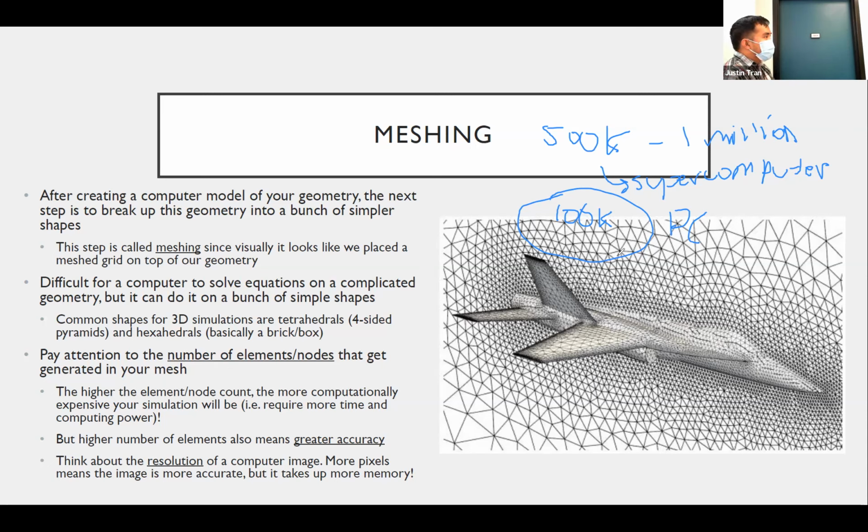The idea is that you start, and this is true for any kind of computational work, with a fairly coarse mesh. You start with something fairly small. You run it on your own computer. You debug most of the issues. Then once you feel confident in all the settings, all the boundary conditions, you increase the mesh and you ship it off to a supercomputer. Because usually, and for this class you don't have to worry about it, I've secured enough resources, but generally speaking, the time and the amount of resources you can use on a supercomputer are pretty limited.